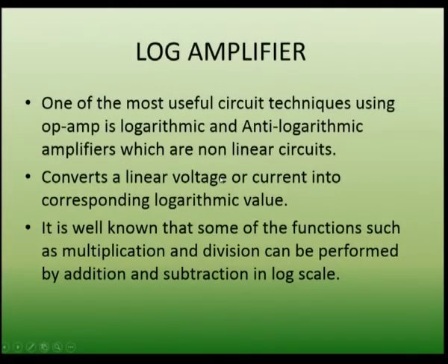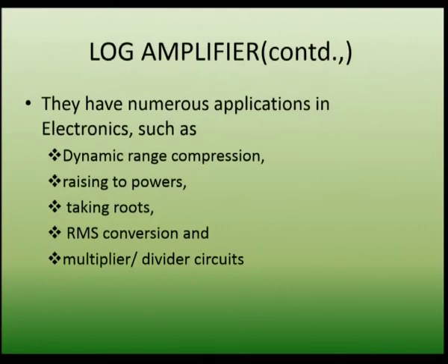The log amplifier: one of the most useful circuit techniques using log amps is logarithmic and anti-logarithmic amplifiers, which are non-linear circuits. It converts a linear voltage or current into the corresponding logarithmic value. It is well known that some functions such as multiplication and division can be performed by addition and subtraction in log scale. There are numerous applications in electronics such as dynamic range compression, raising to powers, taking roots, RMS conversion, and multiplier and divider circuits.